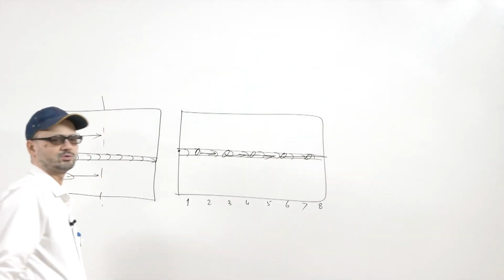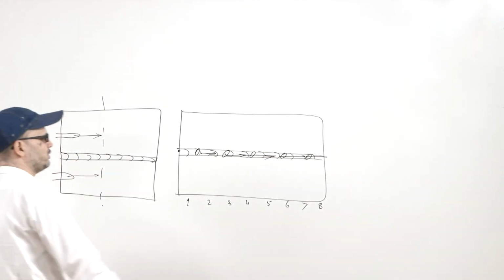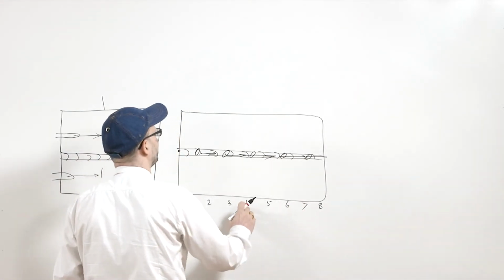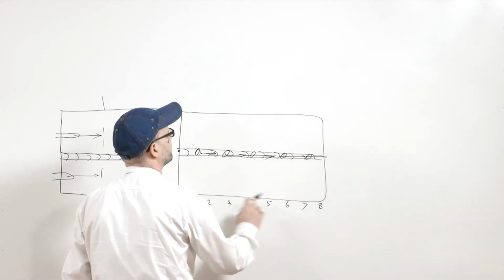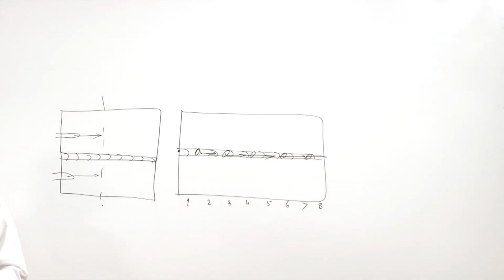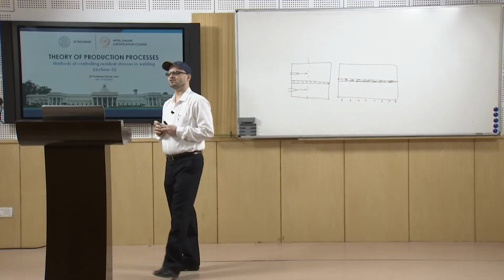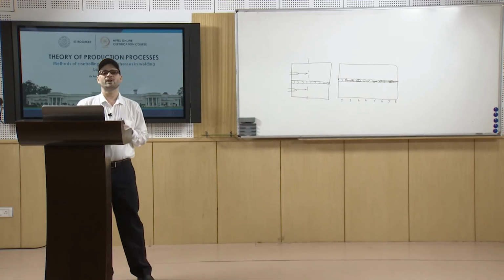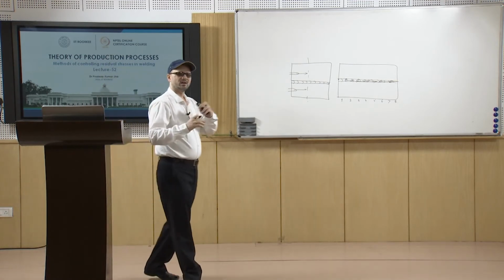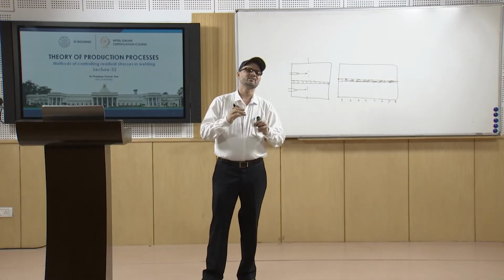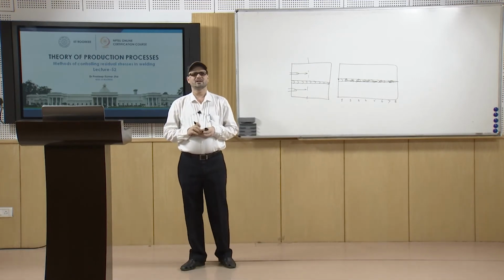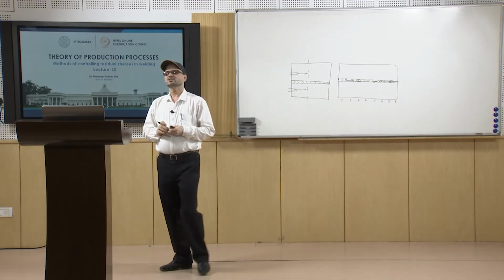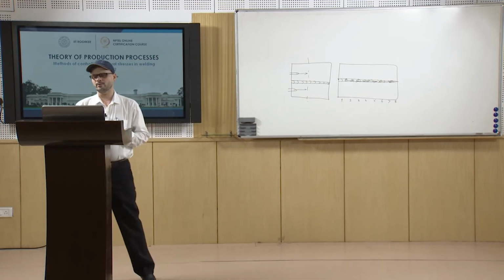We may do the first one here, the second one here, the third one here, then the fourth one here, fifth one here, and 6th and 7th, like that. That is the concept of the skip welding technique. These techniques basically reduce the value of the residual stresses.